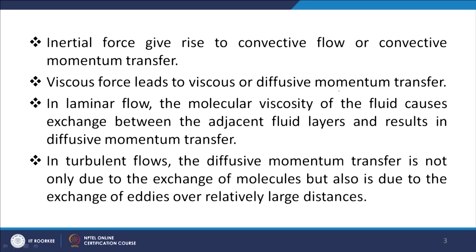Whereas, in the case of turbulent flows, if you recall, here the diffusive momentum transfer is not only because of the exchange of molecules at the molecular level, but it will also be because of the exchange of eddies.